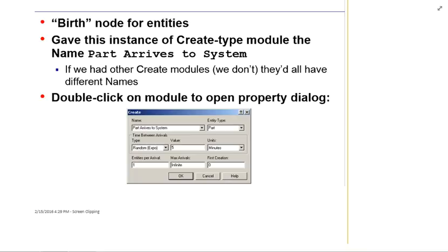And normally you would name that something that means something. So say I had a bracket coming into the system, and I had a plate coming into the system, and then a bolt and a nut coming into the system, and I'm going to bolt the plate to the bracket with the bolt and nut, I would name my entity types: bolt, nut, bracket, plate. And that just gives you a good visual again of what you're actually getting. So that's the entity type, important to bring that into some sort of a useful name that you can use in the simulation.